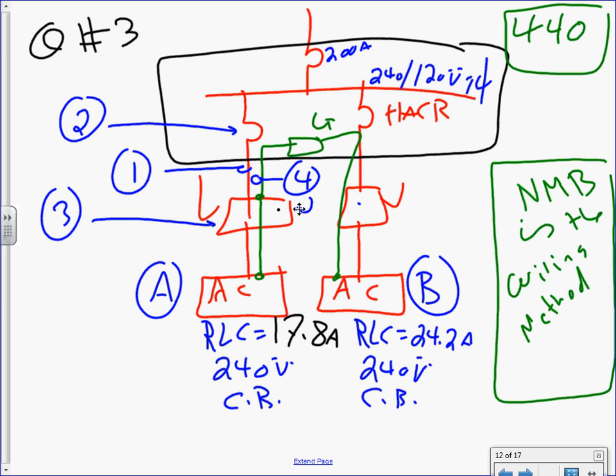The controller. Remember what we did before? We always looked at the controller. Why don't I size the controller? Because 99.9% of the time when you have an AC system, a chiller, the controller will be provided by the manufacturer. So we did not mess with the controller, and it's really going to be similar to sizing a controller for a motor, based on the locked rotor current, the voltage, and the horsepower. Okay, any comments, guys? Any questions about these? Everybody knows what we're doing?